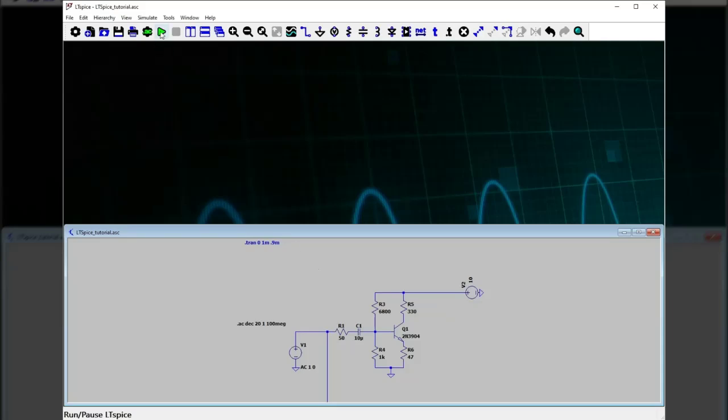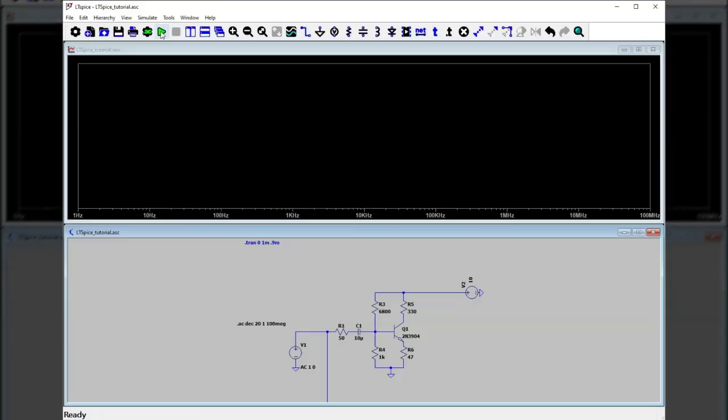So I'm going to run this, and I get my window here, and now I have to tell Spice what I want to see. So let's look here and see what's going on at the output of our source. This is a 50 ohm source, a voltage source, and a series 50 ohm resistor. If I click here, I'll see the voltage on the input.